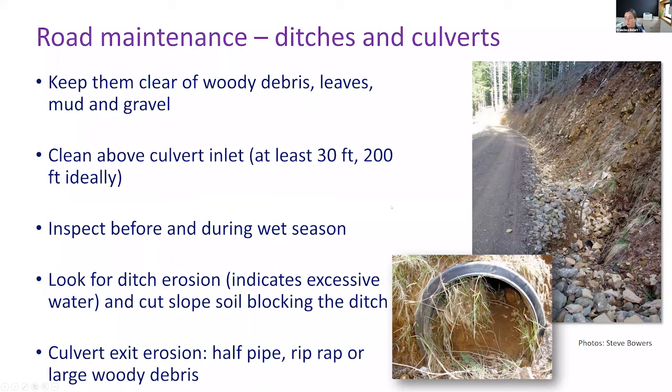The other one is ditches and culverts, and this is when the shovel comes in handy. Keep all of those ditches and culverts clear of woody debris, leaves, mud, and gravel, because those will seriously impair the ability of the water to flow wherever it needs to go, right? For the most part in culverts, try and clean above the culvert inlet, so debris cannot just go straight into it. Inspect all of these before and during the wet season, especially after a big storm.